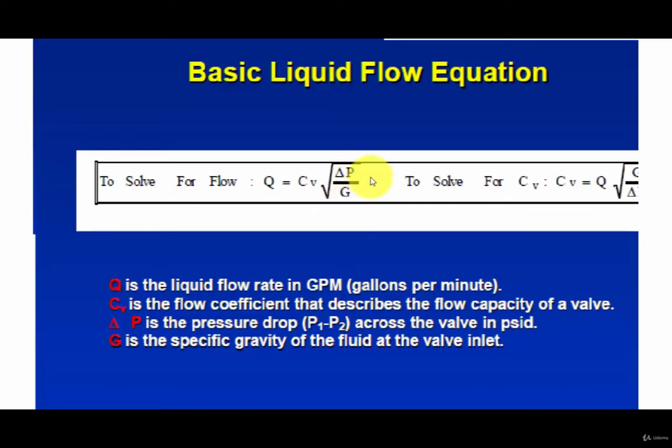So if you go to the valve vendor, he will ask for your process CV. That can be calculated using the maximum flow, dP, and specific gravity, that is, the type of liquid. So you calculate the CV, go to the vendor or manufacturer of the valve, and he will provide a suitable valve with that particular CV, a slightly higher CV valve. That will suffice for your flow application. So that was the philosophy of flow coefficient.